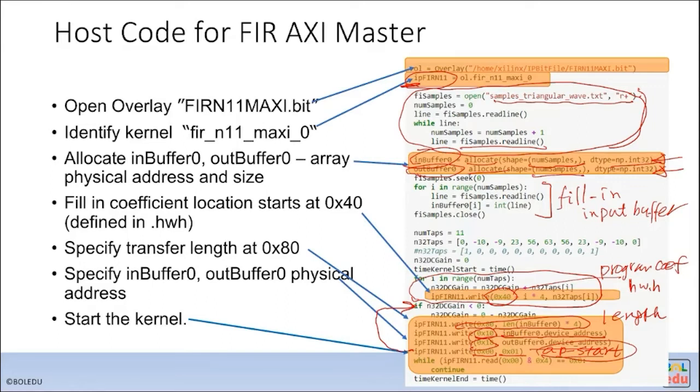Okay, the whole embedded system doesn't have any protection mechanism. It doesn't have an MMU to guard you from messing up the system memory. So you simply write to a random address, and maybe just write over the kernel function. Remember, those DMA addresses access the system memory directly. It doesn't go through the OS, so the OS has no way to prevent any malicious code or any access. There's simply no hardware mechanism to prevent that. So when you do embedded programming, there is no protection whatsoever.